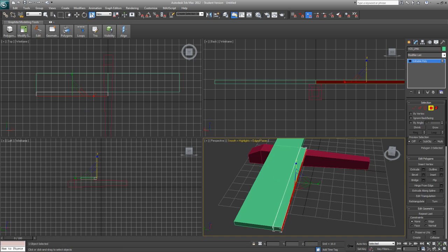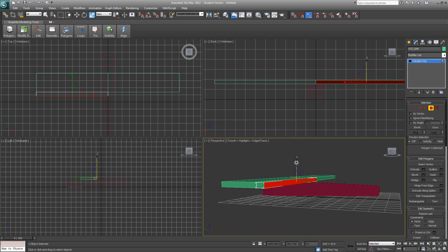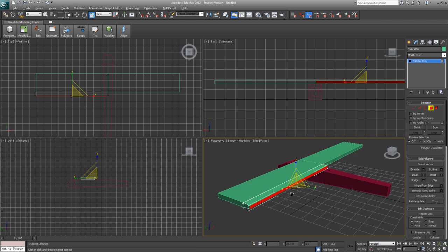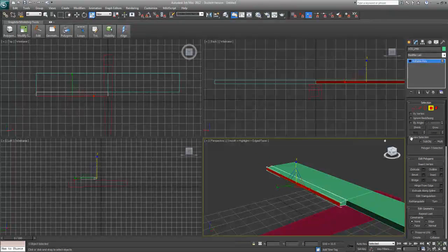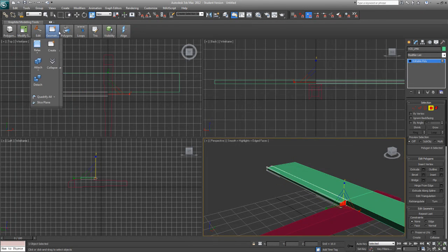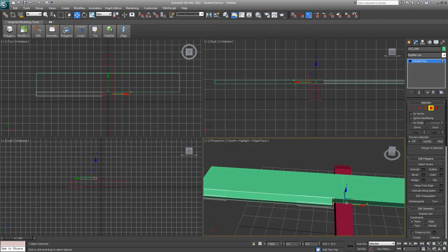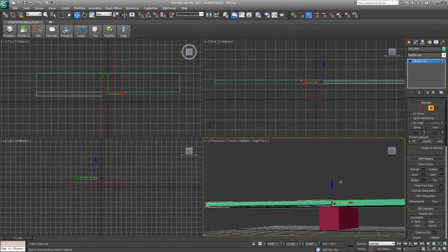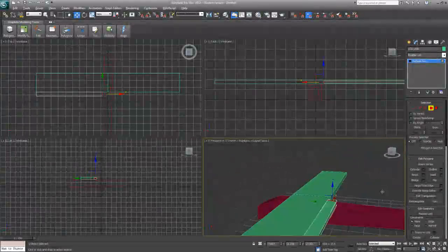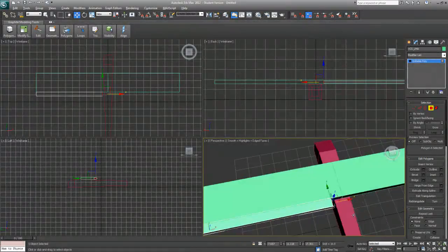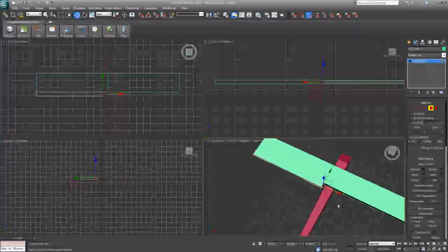And while we're here, why not take it just in the Z-axis, just by grabbing this handle, pull it down so it's got some sort of taper. And now that that's done, let's grab this poly, go back to the move tool, move that outside the fuselage so that it can actually pivot. Okay, so we got a very basic